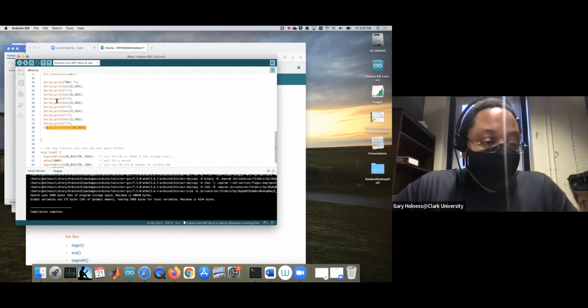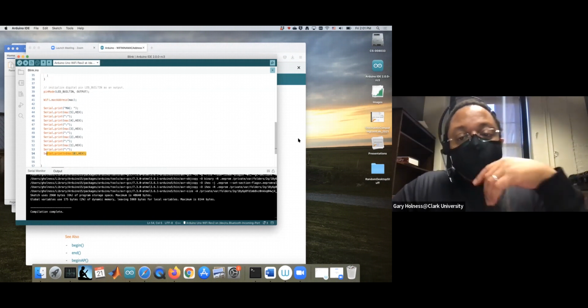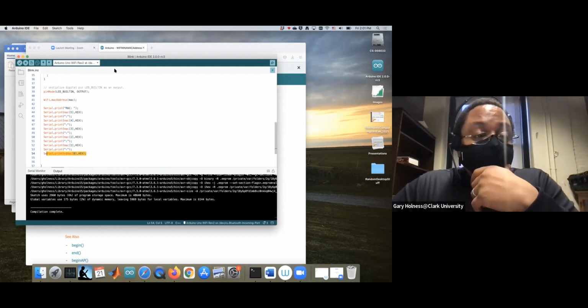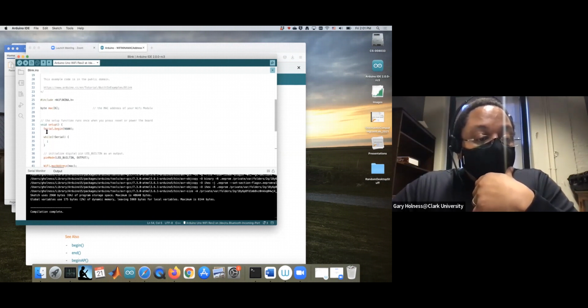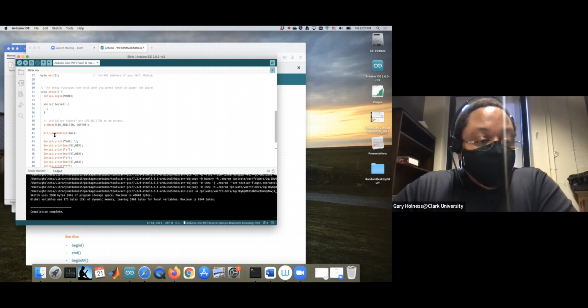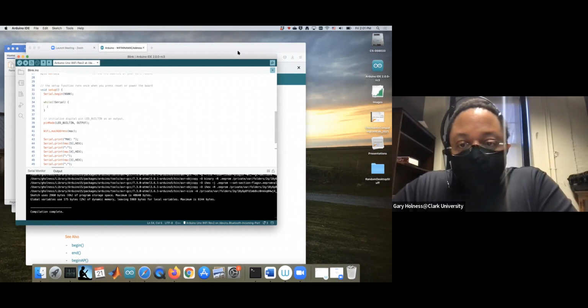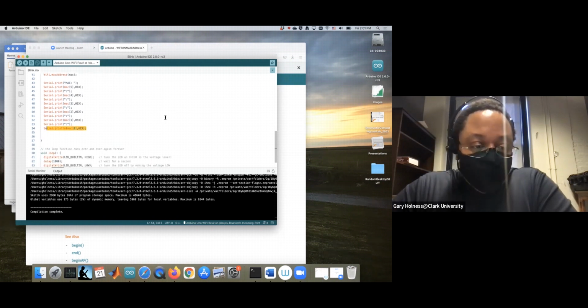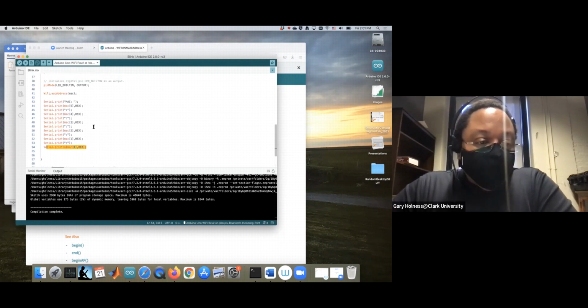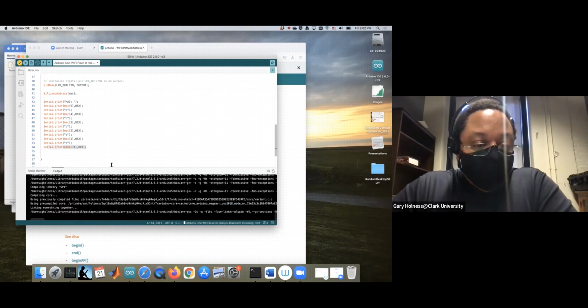So let's now take our board and compile this. I've done two things here. I started out with the Blink demo, and I added to it the bootstrap of the serial monitor to get the serial runtime running. Then I Google searched for the WiFiNINA MAC address print example, and I just copied and pasted that. So let me go ahead and compile that.